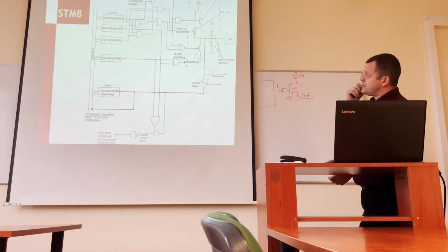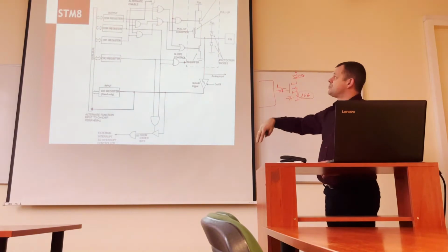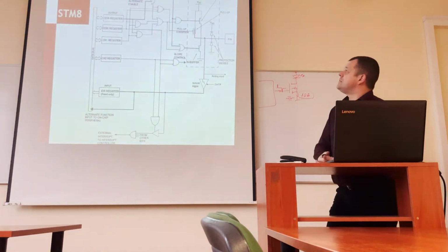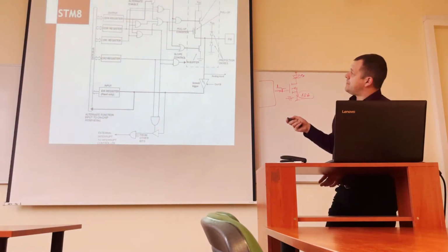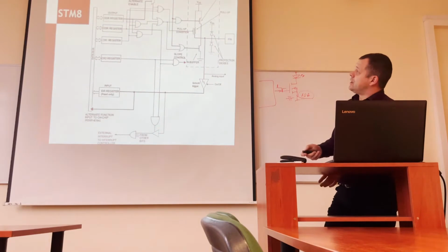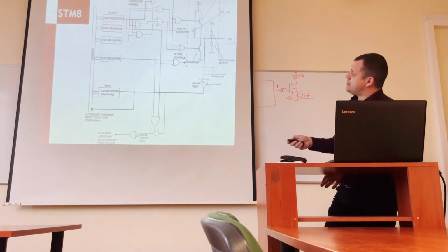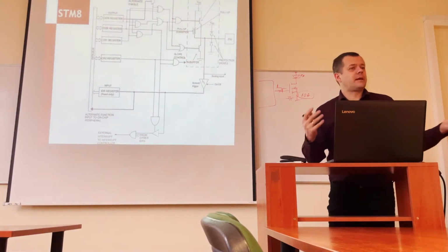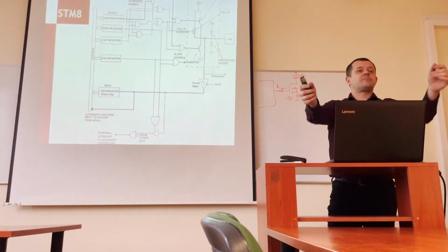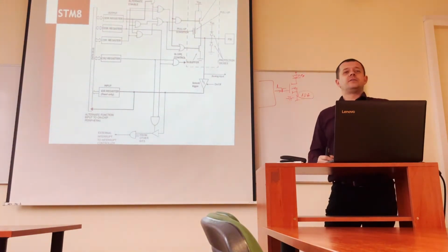So if you want to modify the pin to be input or output, then you have to change the DDR register, so the appropriate bit in the DDR register. For outputting data, we've got a dedicated ODR, output data register, and for reading, we've got the input data register. Here in this microcontroller, different names, but that's not always. Sometimes microcontrollers have a common port that you can read or write.